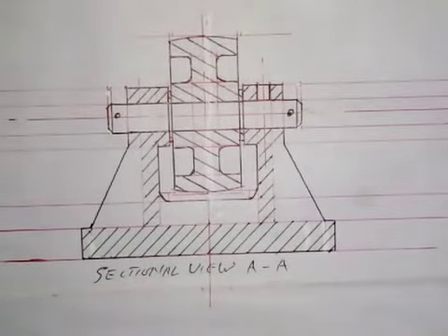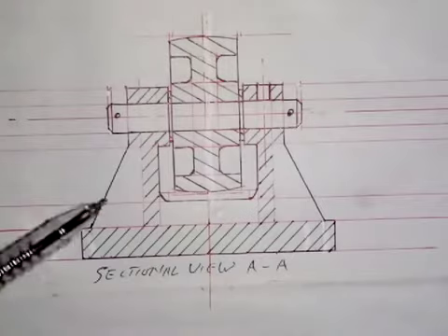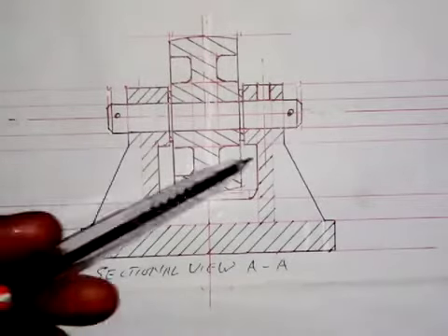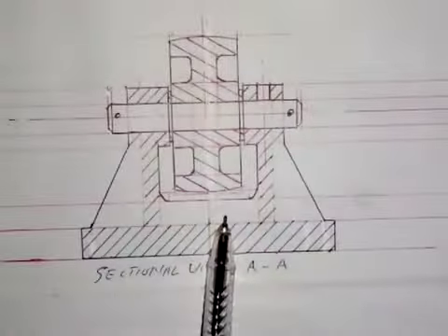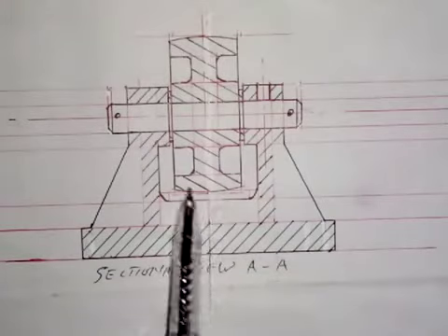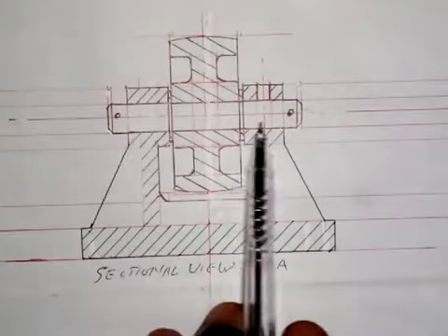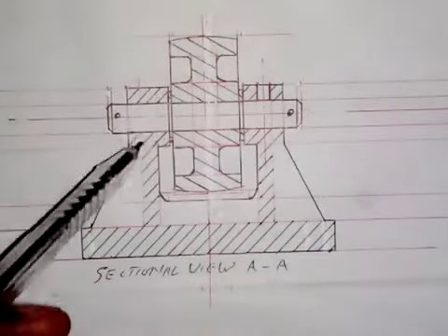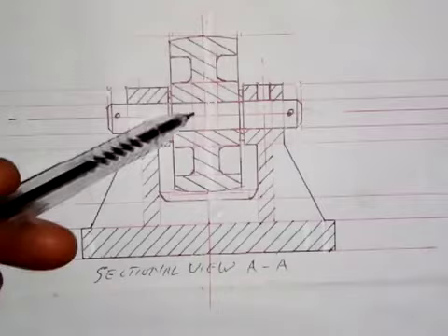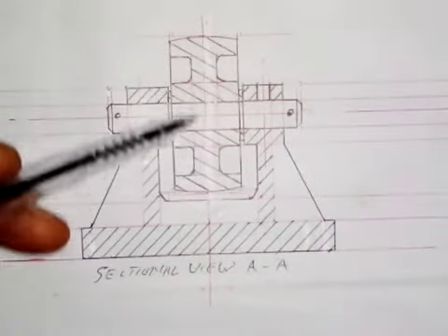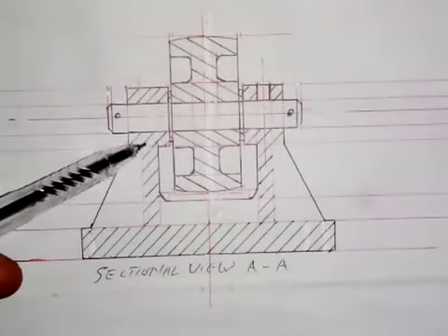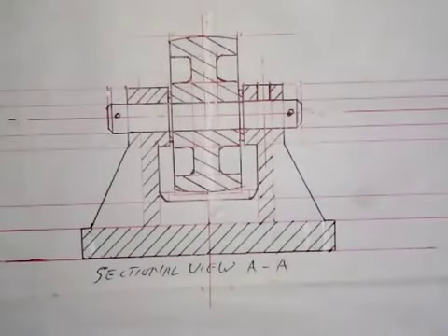Alright, so this is the sectional view. This is how it will look. Just look at the part that I hatched here. I hatched the solid part. This is a web. We are not to hatch it. This is also a web. We are not to hatch it. We also have a web here, not to be hatched, and we are not to hatch the pulley spindle. But we need to hatch the washer and this solid part of the pulley, and also this part of the main body. So it's as simple as I've shown it here. All you need to do is to practice.